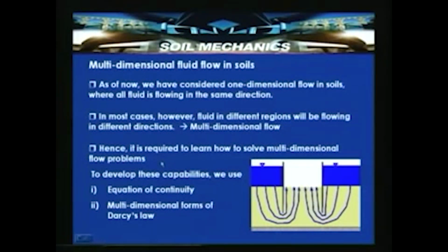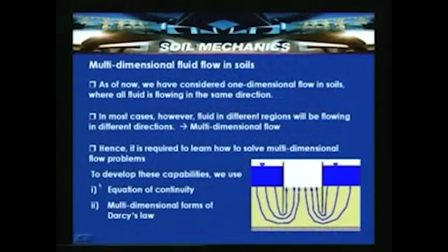To develop these capabilities we use the equation of continuity, which is based on the conservation of mass, and the multidimensional forms of Darcy's law. With the help of these we will arrive at the equation of continuity and its solution, and its application will lead us to calculating the seepage problems involved in earth dams or sheet pile walls.